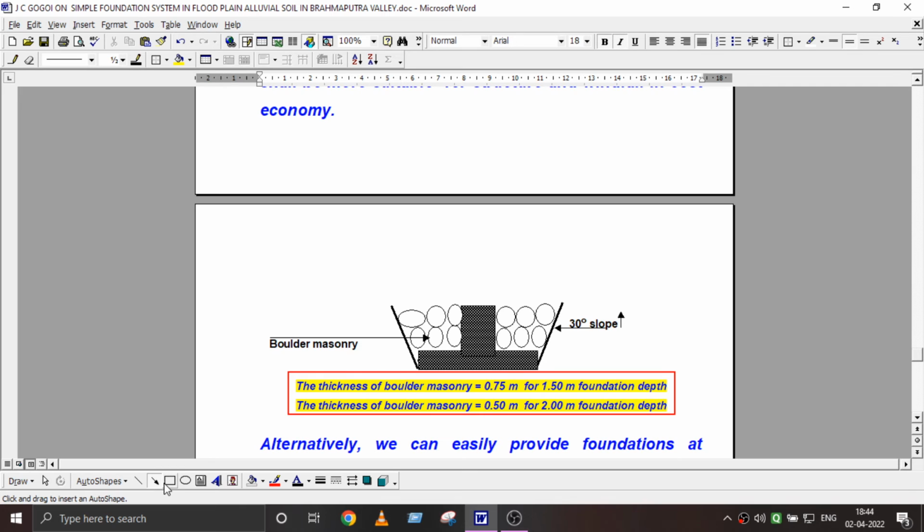This soil will give a surcharge effect against the uplift moment of the foundation. Overturning forces uplift this when there is a much higher load, then this side will be going up and this side shall be going down.